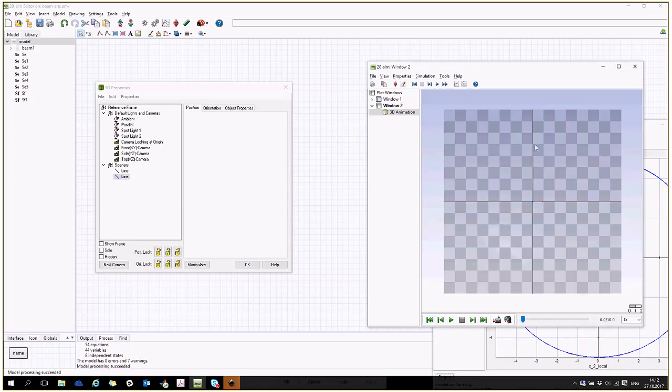So for example, if you have done it right, then the cylinder should appear vertical for the second beam, and the two end points should be at the same point for all simulations. If they are departing somehow, then that means there are some errors in your connections.